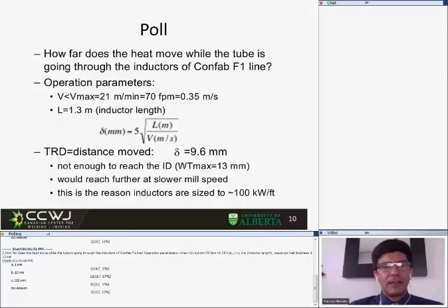If heat transfer alone is not enough, then we need to bank on the electrical reference depth. We have to make sure that the electrical reference depth covers the whole thickness of the tube. One or the other has to cover everything. Otherwise, the outer surface of the tube would be much hotter than the inner surface at the part of the seam. So this simple exercise, and it's such a simple formula, actually helps us think.